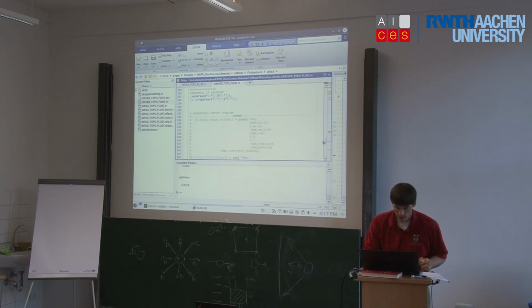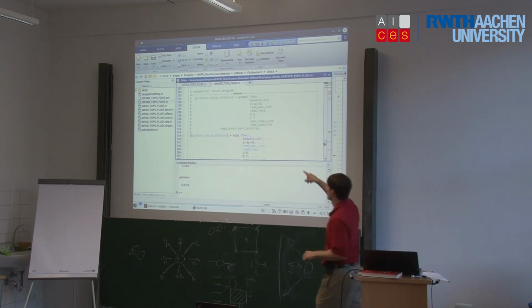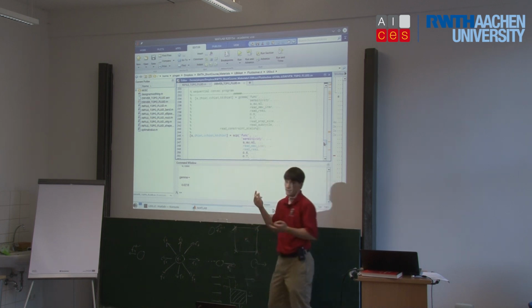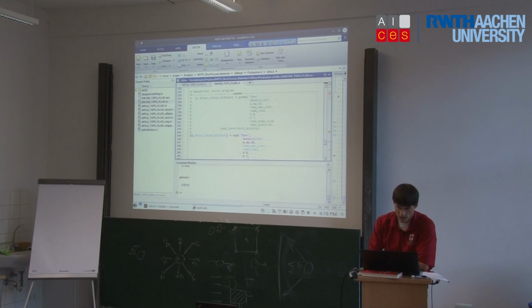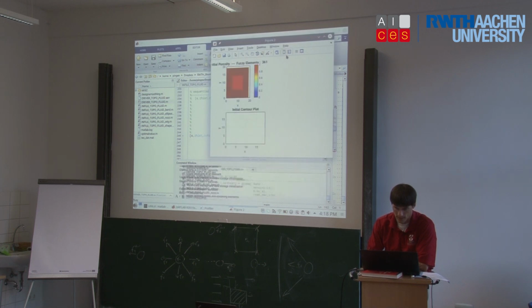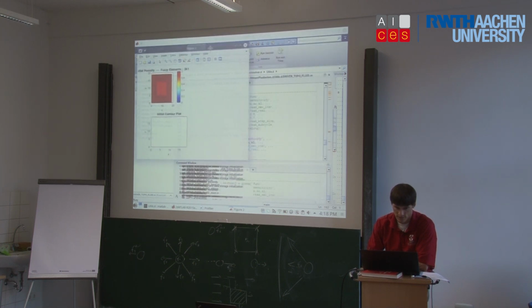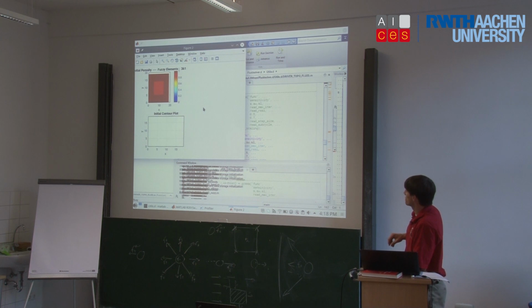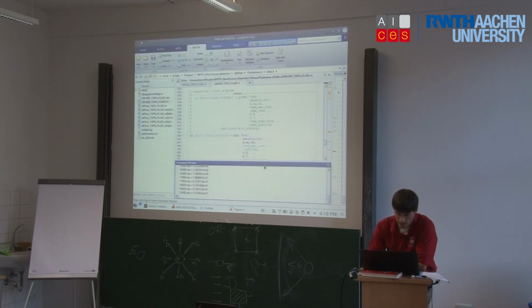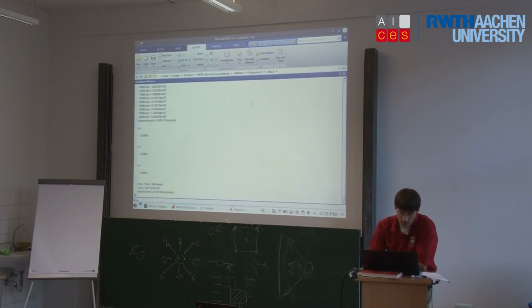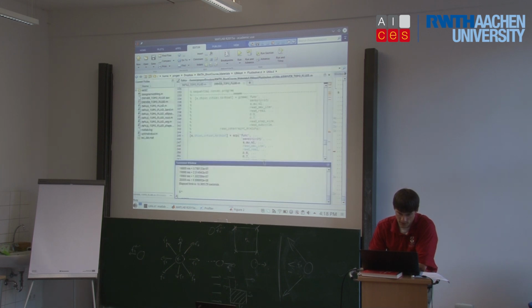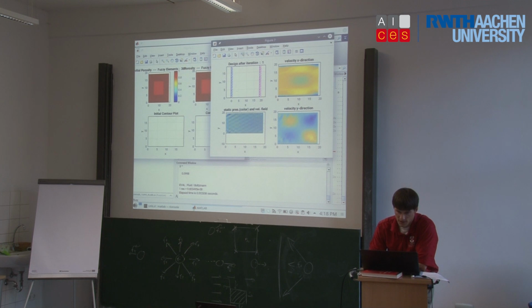Down here, it then calls the SCP optimizer. As an alternative, you can just try the GCMMA instead of the SCP optimization algorithm. So when I run this, I execute this code and see if it all works. Okay, these are the initial conditions. That's just the initial porosity distribution. So there you can kind of see the algorithm converging.